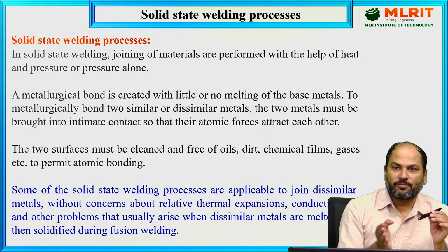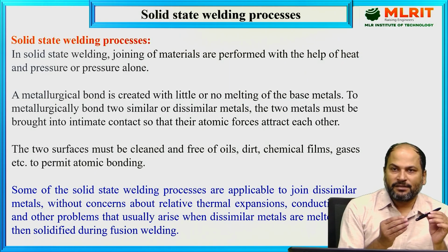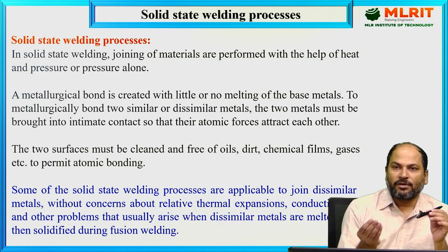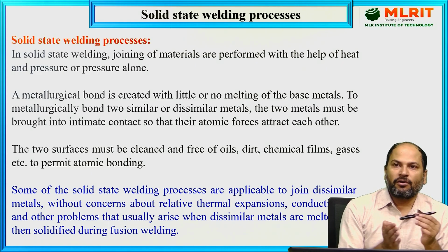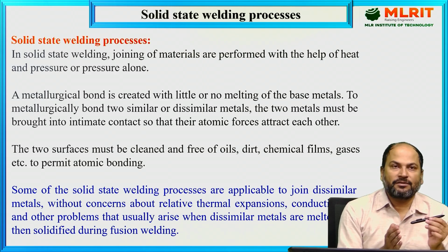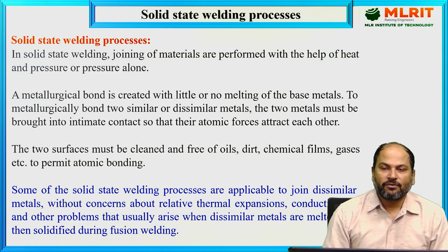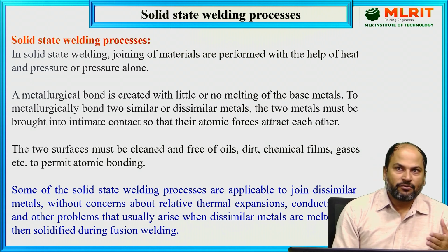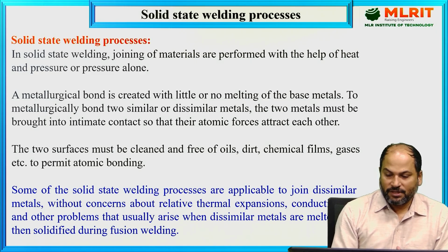So far, the processes we have discussed, almost all the arc welding processes, then resistance welding, thermite welding, and plasma arc, were all in the category of liquid state or fusion state welding. But today we are going to discuss solid state welding, meaning the material that we are going to weld is not going to change state from solid to any other form. That's why it is known as a solid state welding process.